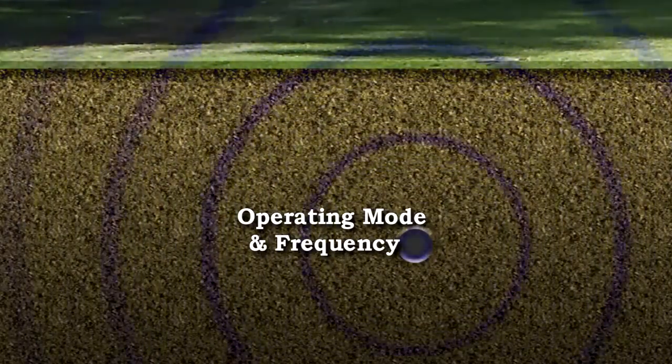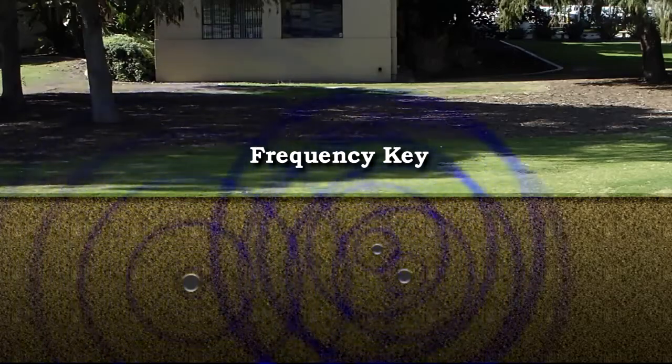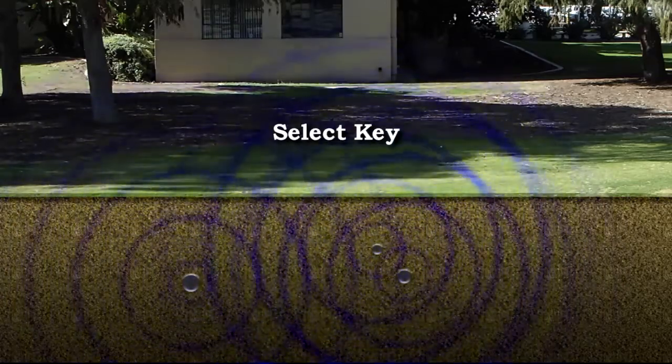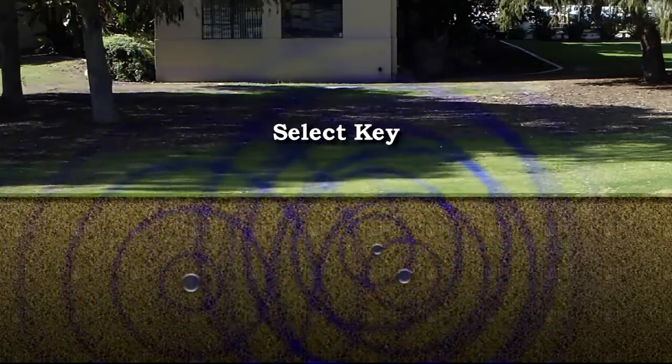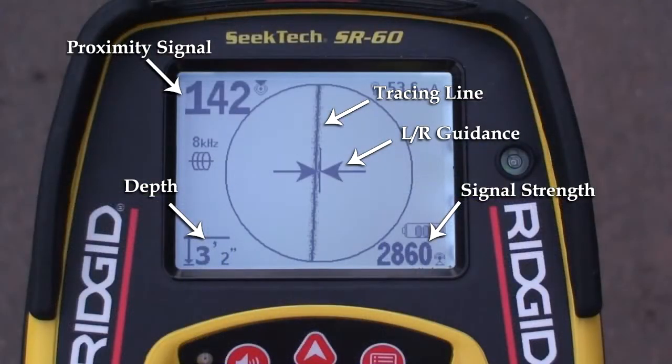In favorable conditions, this is generally true. Quite often, however, conditions exist that interfere with or distort the signal, which can make the signal readings less reliable. Some common sources of distortion are signal bleed onto adjacent conductors, turns, tie-ins, and large metal objects such as manhole covers, vehicles, and fences. The SR-60's 5 main signal readings help you spot signal distortion quickly. Because all 5 readings are available on screen while you locate, you can quickly compare them to determine whether or not the signal is reliable. Let's take a look at these signal readings and see how they work.